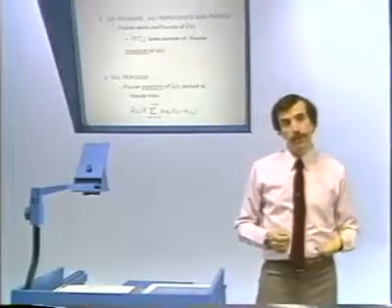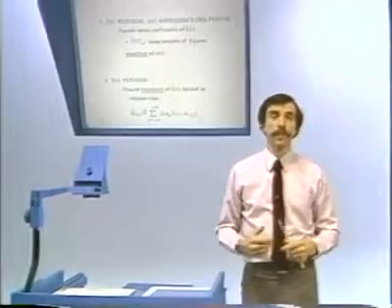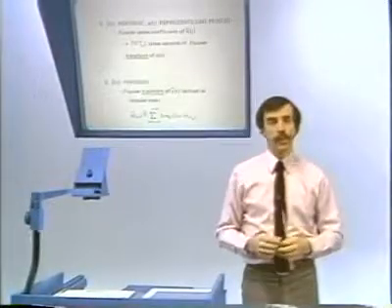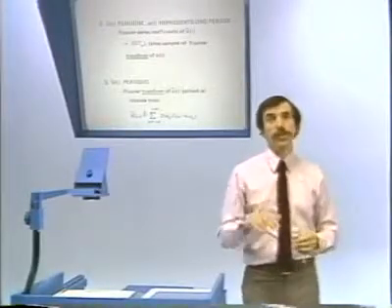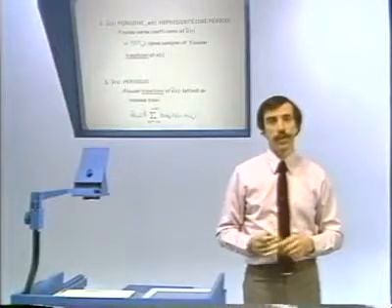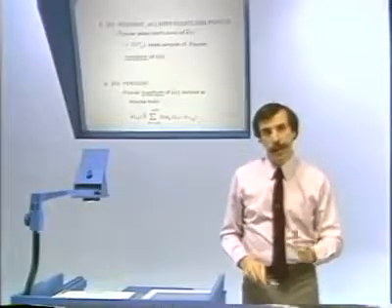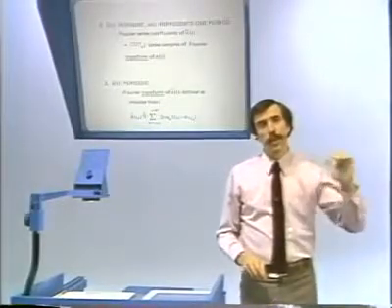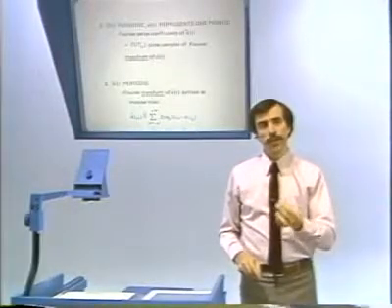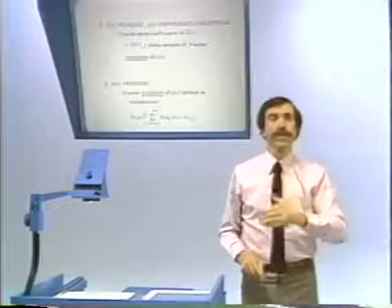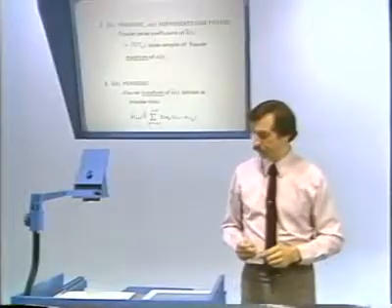What I pointed out at that time was that if we define, and take it as a definition, the Fourier transform of the periodic signal as an impulse train where the amplitudes of the impulses are proportional to the Fourier series coefficients, and we simply plug that impulse train representation into the Fourier transform synthesis equation, what we end up with is the Fourier series synthesis equation.